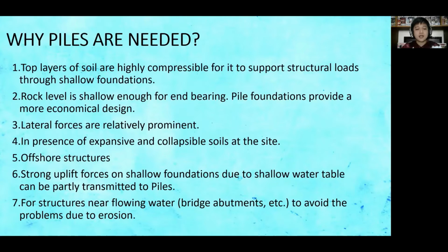Second, rock level is shallow enough for end bearing. Pile foundations provide a more economical design. If rock level is shallow, we do not need a very long pile, and it might be more economical than an over-designed shallow foundation. Third, lateral forces are relatively prominent, such as earthquake.